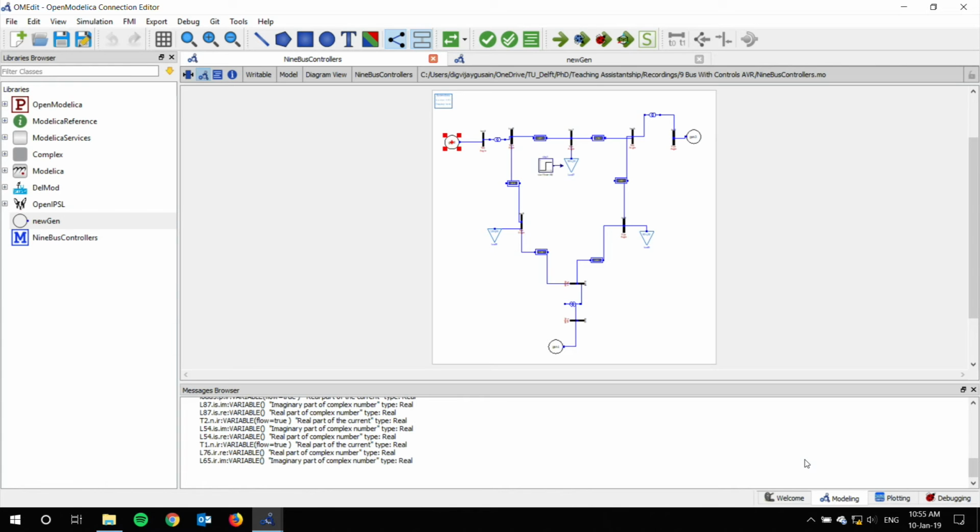A speed governor on each generating unit provides primary speed control function, while supplementary or secondary control originating at the central control point allocates generation. Frequency control was detailed in the previous lectures, so we will not repeat the theory part here. The governor model used in this session is given below in figure 3 of the modeling companion. We will now add governor modules to the generator systems.